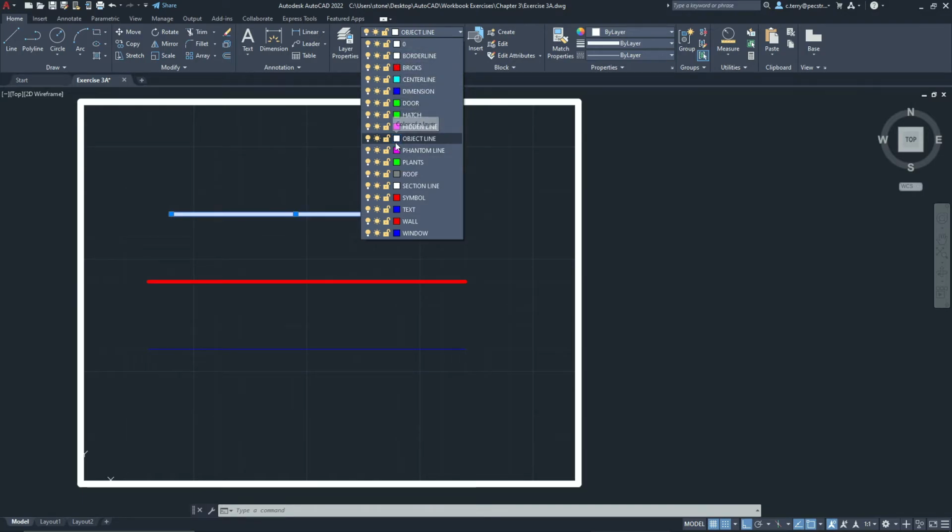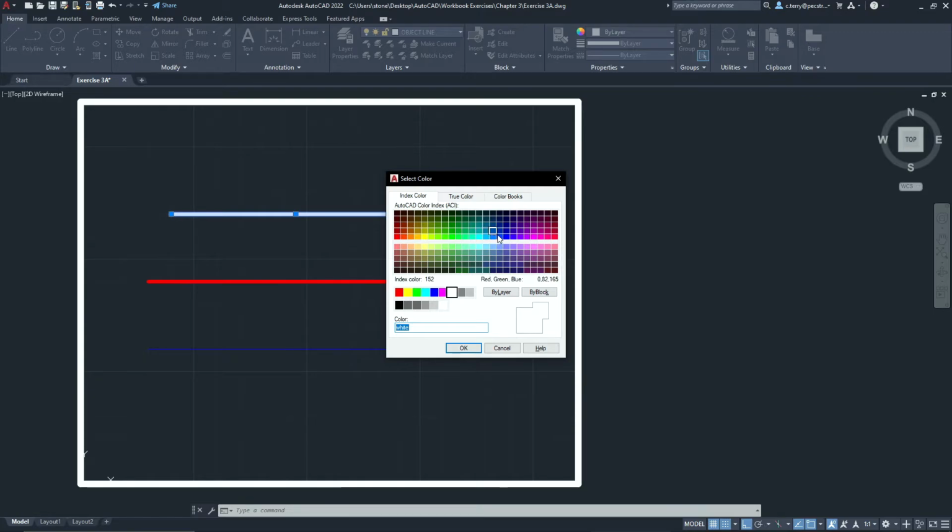If I were to try to change one by clicking on it, I can now go here to this index of colors and I can click one of the base colors in AutoCAD. I can change it to these different colors based on number, and it gives you the RGB over there as well for what it is. So there's the specific color you want. You can click and say, if I wanted this yellow one, or this kind of mustardy color, or maybe this light purple pink, something like that. You can change all these without modifying anything to the layer itself.